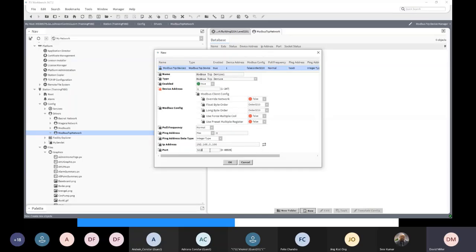It has to be a completely different IP address. So you can set up two IP ports, each with its own IP address, but the IP addresses have to be significantly different. They can't be in the same subnet. And what happens then is that when you say IP address 192.168.0.100, the FX80 knows which IP port to use because it'll be the IP port that's in the same subnet as the target.